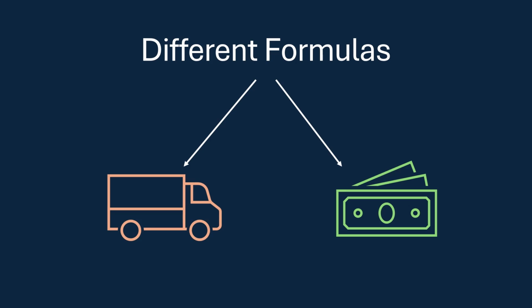Throughput is also looked at through the view of money, where a calculation is used to see how much of the production is turned into money, not necessarily just produced. That said, the definition I have used in this video of units produced over a unit of time is the most basic and mainstream definition. Second, more is not always better. As I mentioned, producing more inventory is not always good. Your throughput may be high, but if you're not selling the inventory, it is actually hurting the company, as it is tying up cash in undesired inventory.